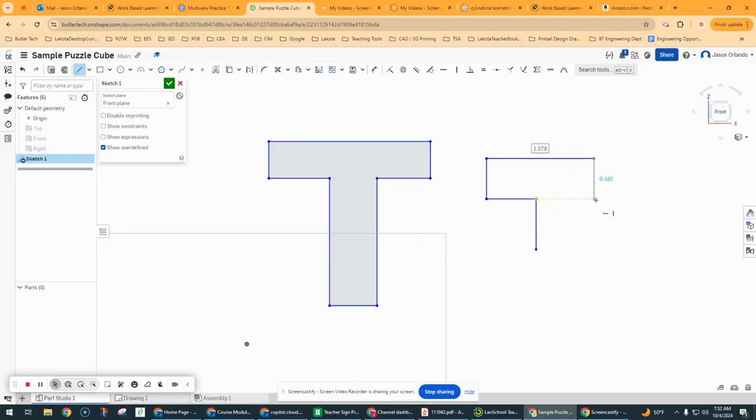If I click right here where I'm getting that dashed orange line, and so moving across, right, this has to now show perpendicular to the previous, so kind of the same as horizontal. So it's creating these auto constraints based on where I have my mouse, which I'm fine with. The shape that I want to create is going to have these right angles, okay? So hopefully that makes sense that I've created a little closed area where basically I've constrained a shape, just not a size. So to start to constrain dimension sizes, we use the dimensional constraint, okay?